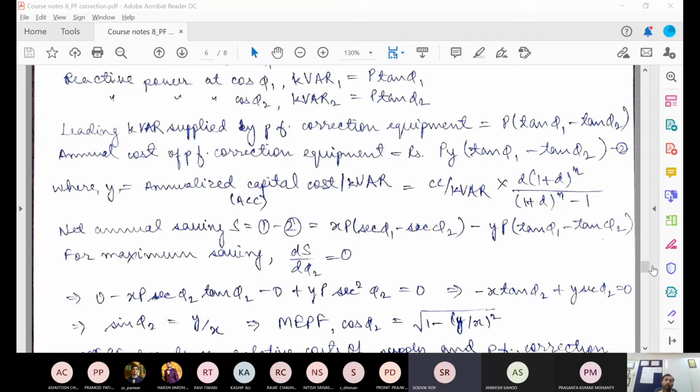Mostly, yes. It depends upon the regulations of the particular electricity regulatory commission. Definitely for 11 kV and higher consumers, this will be the case. One thing which we need to make sure is that a 415 volt three-phase consumer might also be coming in the purview of maximum demand monitoring, or might not, depending upon the regulations from state to state. So that is one gray zone, but definitely 11 kV and above will be coming in this.